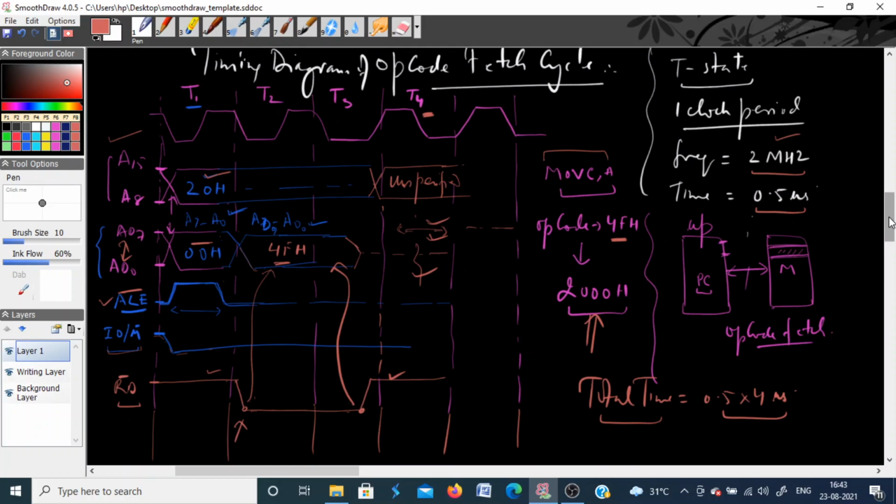Okay, we were discussing these timing diagrams in the last class. So you've seen how the code is fetched, decoded, and executed by the processor. We have taken an example in which we moved the contents of the accumulator into C, right? We discussed how the various control signals are generated and activated by the processor in a sequence. So this is a one byte instruction. This entire operation is executed using a single byte, or in the opcode fetch cycle itself the instruction gets executed.